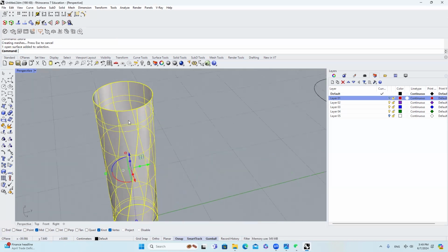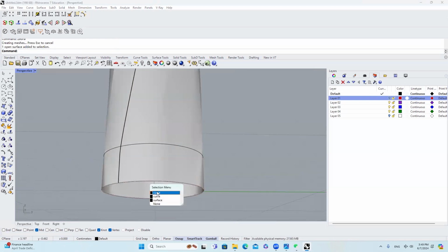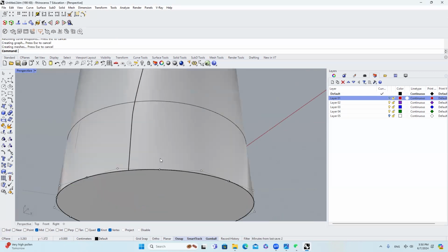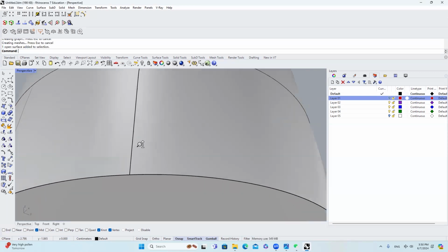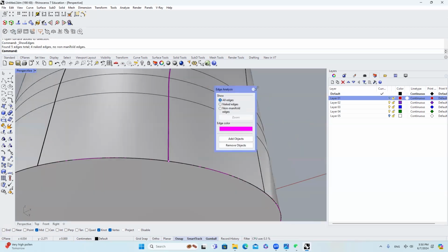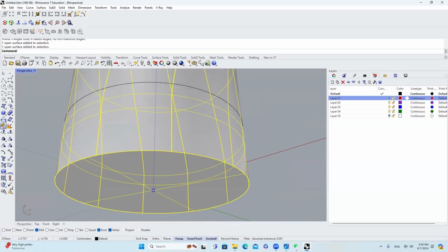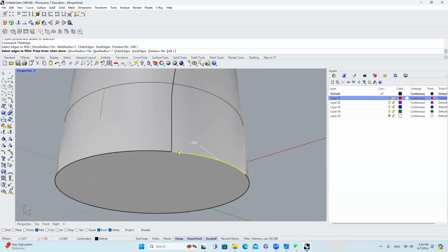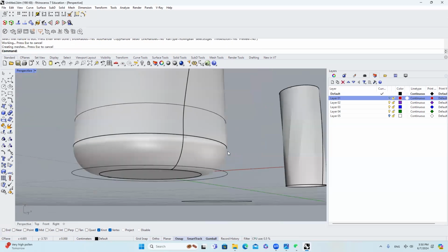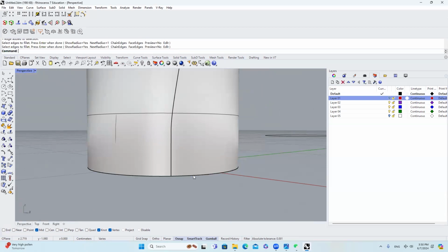And then what we can do for the next is we're going to select this edge, and then we're going to use plane surface. It's a self-interpret surface. That means that this edge has some issue. So let's take a look of the edge condition. Looks fine. Let's see if we have some problems during the process. Let's use fillet edge. It's working. So change the radius to 0.2.